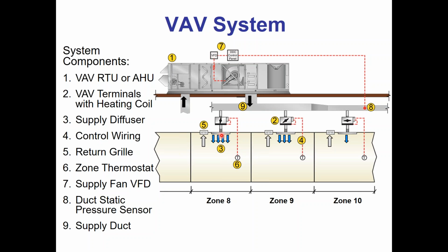My supply air and supply air grills. Now, the diffusers that I'm going to use for supply air also need to be specific for VAV. Just like the air handler can't be a regular constant volume air handler, well, the diffuser can't be a regular constant volume diffuser. I need to have one that has good ADPI, good throw characteristics to it. If not, when I throttle the airflow back to that zone, I throttle the CFM back, if I have a crappy constant volume diffuser, it's going to dump the air straight downward.